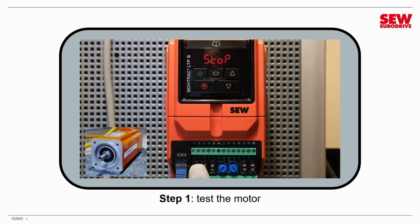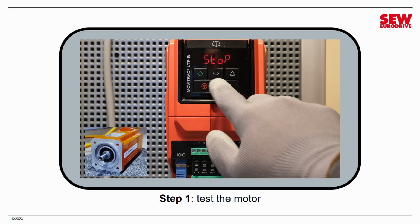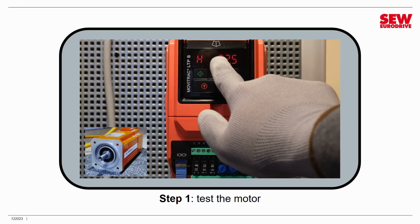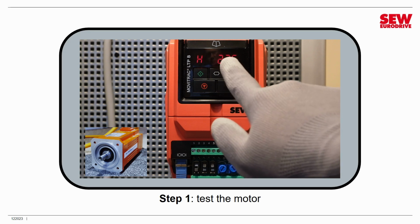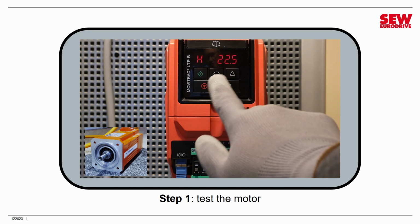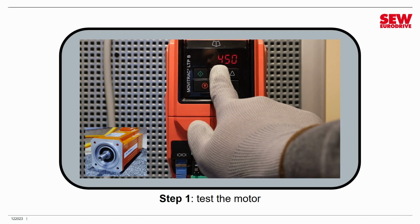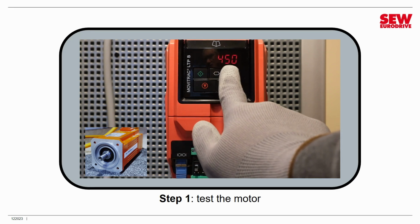So we'll press the start button on the keypad, and that's going to take us up to the minimum speed, which is 450 RPM. Now we're on Hertz display here, so I need to press the navigate button a few times to cycle around to RPM. There we go, 450. So that's our minimum speed.